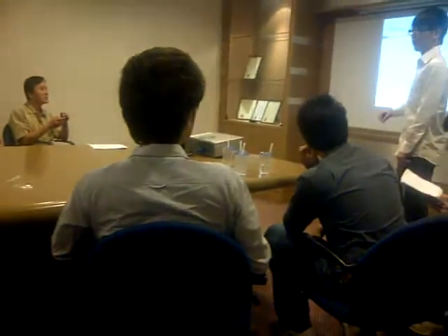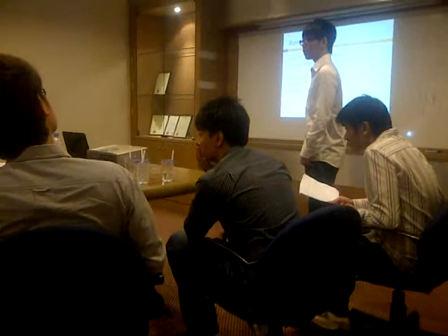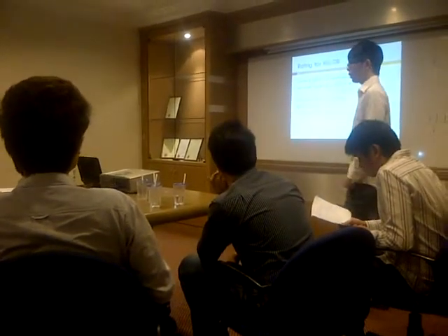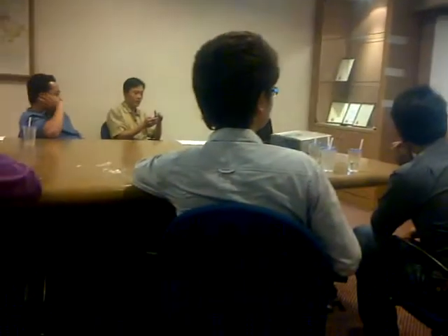Because it's based on the summary that I got. Let me make a very rough calculation. 28 kilowatt, one unit, 28 kilowatt times 1.64 equals one aircon unit already consuming 45 amperes. That cannot be right. When you multiply by the total, how many units? 8 units.